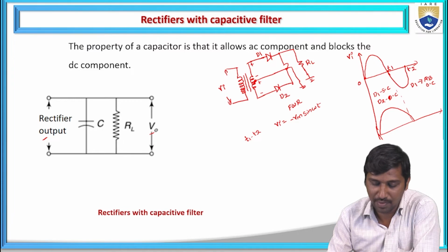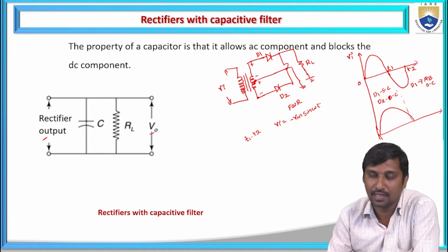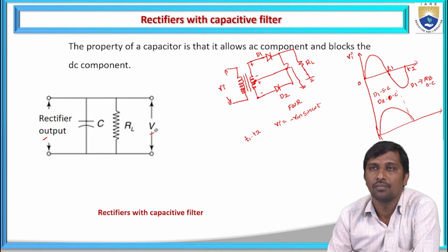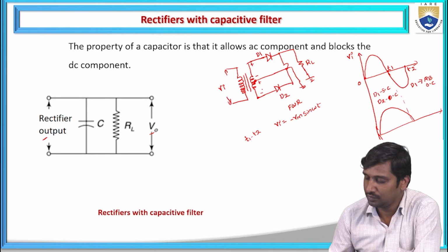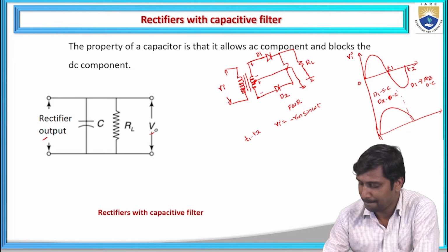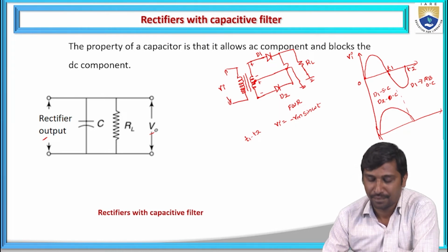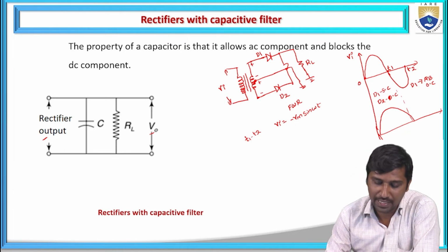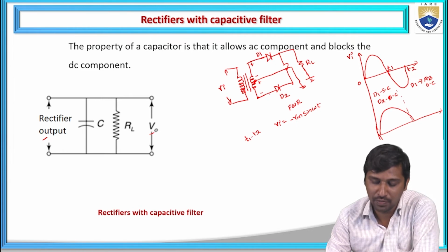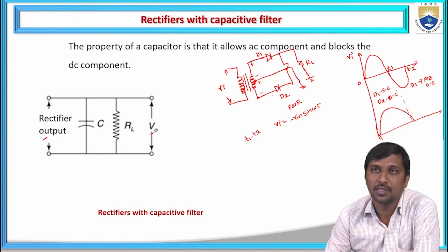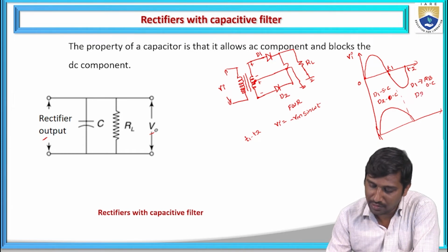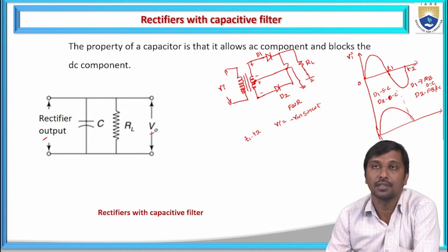Similarly, this node is negative, and the negative magnitude becomes a positive. Hence the positive magnitude is passing through the anode of D2, so at this voltage D2 acts as forward biased, and it is replaced with a short circuit.